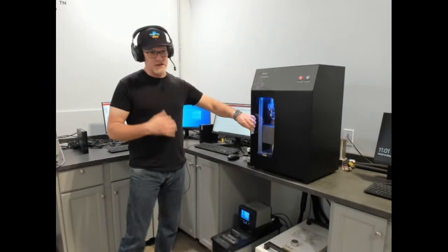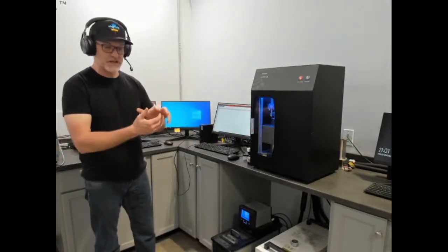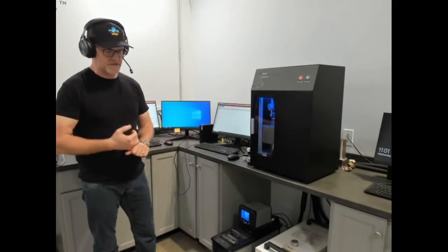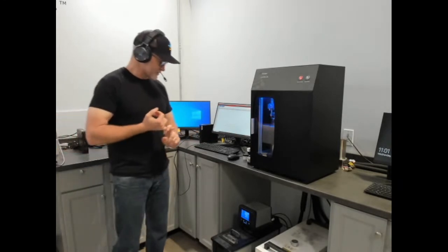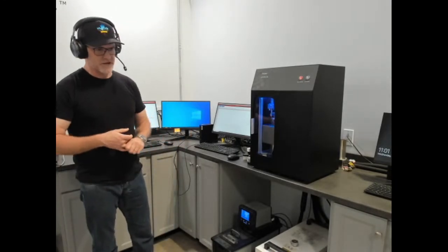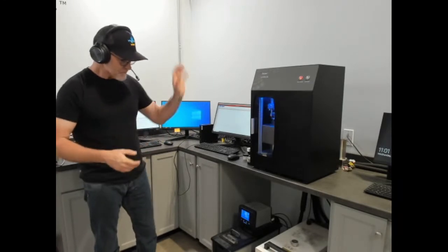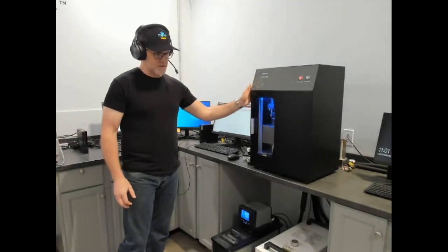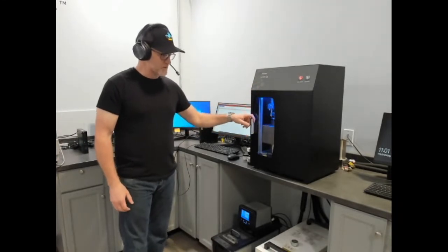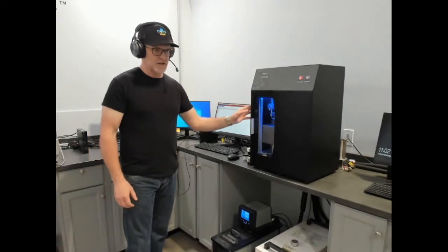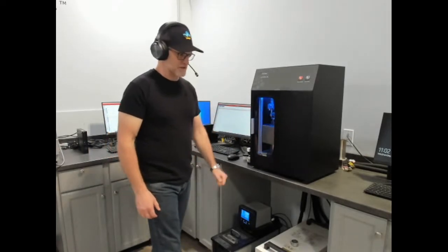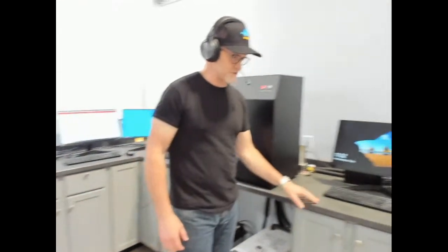So in some of those situations, depending on the degree of that heterogeneity, with that definition, you might need to measure thermal resistance to get a true value. And that tends to be true for complex composites that are heterogeneous in nature and or layered that are not repeating through the thickness. So this is ASTM E1530 for a thermal conductivity range of 0.1 to 100 watts per meter Kelvin. So that's a very critical instrument in measuring such complex materials, which exist in a lot of engineering